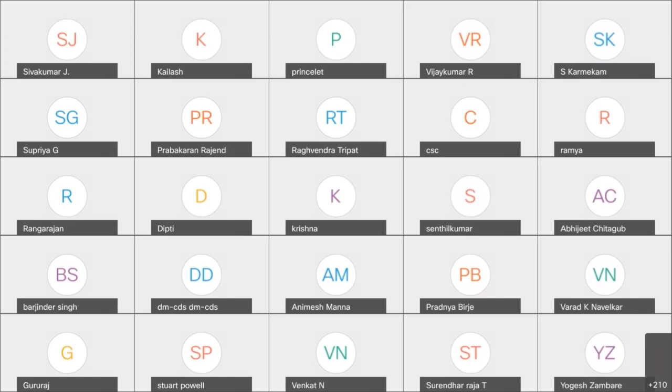Okay, we can change. You mean check for an alternative component? Correct, yes. But sometimes that may not help 100%. In that case, you need to change the design. For example, for one design you might have used maybe 25 components. In case that can be converted to fewer components with a lower failure rate, then probably that will also contribute to your SPFM value. But that would be a major change that your customer may not be interested in.